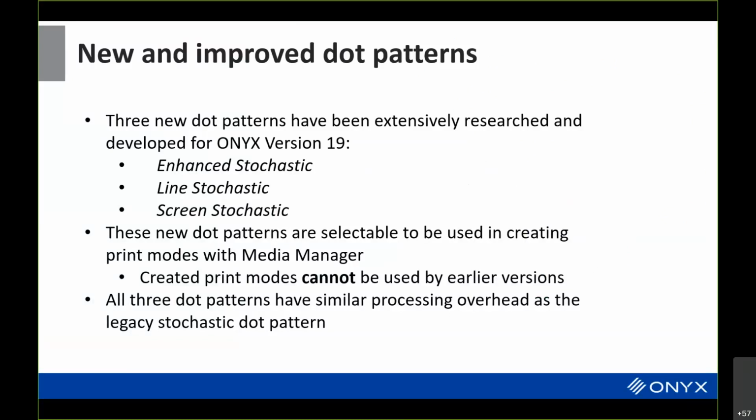Each of these 3 dot patterns is selectable when you're creating new print modes in Media Manager. They can't be used by earlier versions of the software. So if you profile in version 19 using this and create an OML and try to use it in version 12, it won't work because version 12 doesn't know anything about these dot patterns. All these dot patterns have similar processing overhead as the legacy stochastic dot pattern. They just look better, but they process basically the same under the hood.